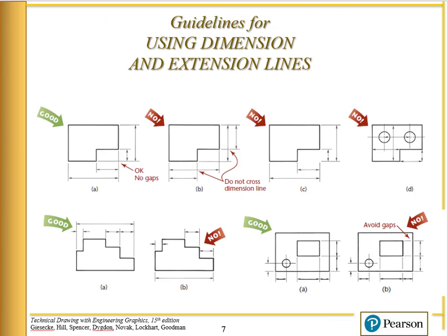Here are some guidelines for using dimension and extension lines. This picture A here, that is a good practice. We have the extension lines crossing here. It's all laid out good, so there's no gaps, so it's okay. Now, in this one over here, we have dimension lines that cross extension lines. Man, that's not good practice.